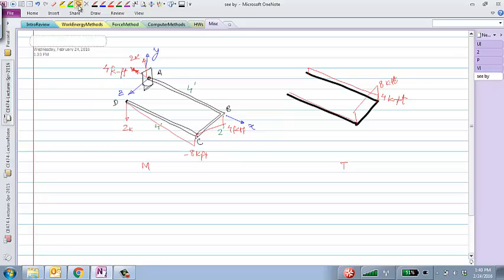What about the bending moment in this guy, in AB, the last leg? So, couple of things to note here. There is torsion of 8 kip feet out here, right? If I take out this leg, maybe keep this back here. So if I look at this structure, this leg BC is under a torsion of 8 kip feet. That torsion will translate into bending in the leg AB. Hopefully you can see that.